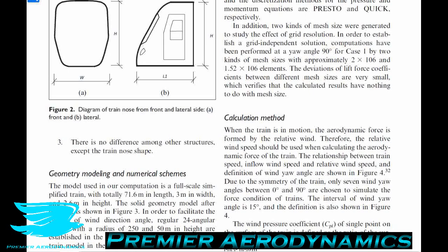So having even people in your wind tunnel area changes the density of air because you are there, which means that you're going to have errors in your wind tunnel data. What's more, the density of air changes even more than 2 to 4% between days, weeks, months, and seasons. So 10 to 15% changes are very normal, which means that you need to take them into account when you have your experiments. What's more, if you don't take them into account, then you are not only getting random error in most of your experiments, a lot of the stuff you find is going to be in that random error, and you can't really be sure that what you're finding is true.